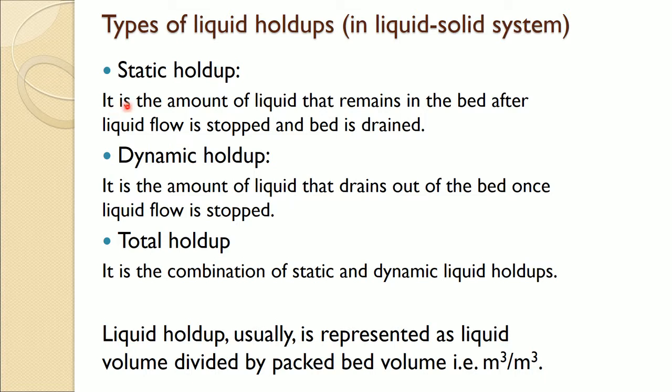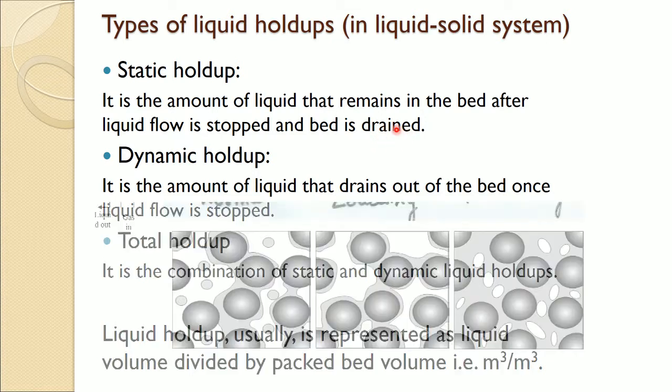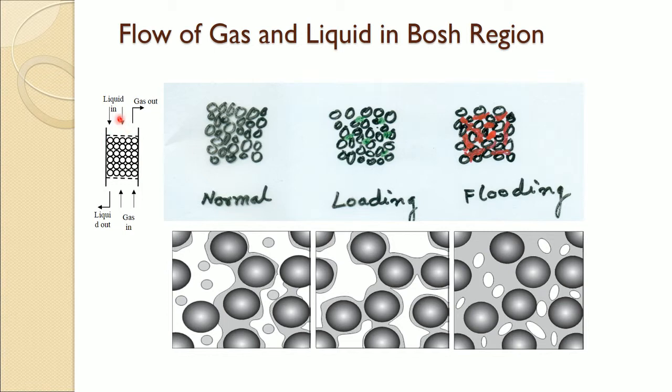The static holdup is the amount of liquid that remains in the bed after liquid flow is stopped and the bed is drained. So, if you stop the liquid flow here and let the bed drain, in between the particles some liquid will stay there, and that is what we call the static holdup.